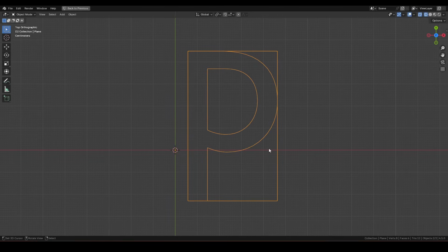So, what I'm going to be doing is storing all the pivot points of interest as attributes. Blender provides 7 pivot points as built-in options. 3 points along the bottom: bottom left, bottom center, bottom right. Midpoint in the center. 3 points along the top: top left, top center, and top right. I'll be adding 5 more points on top of them. Middle left, middle right. And 3 along the baseline: 0 left, 0 center, and 0 right. Might be an overkill, but we'll end up with 12 selectable points.